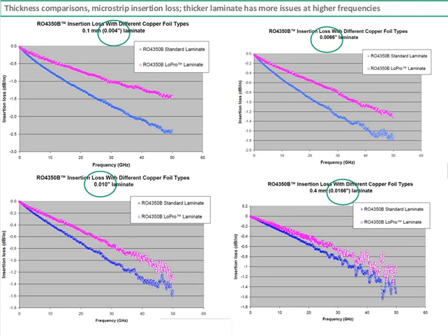Another thing I wanted to point out in these charts is the insertion loss curves. And you can see the thin circuit, upper left, has insertion loss curves that are actually pretty smooth. Looks like they're pretty well behaved. And then when you go to the right, 6.6 mil thick, out at higher frequencies, around 40 to 50 gigahertz, you see that there's a little bit of noise in the insertion loss curves. Bottom left chart's thicker again, 10 mil thick. You see more noise at higher frequencies. And then finally, the bottom right, 16.6 mil thick, you see a lot of noise out around 40 to 50 gigahertz. And that's really because as you go thicker, you're getting more of these spurious wave modes that are interfering with your quasi-TEM mode that you want.